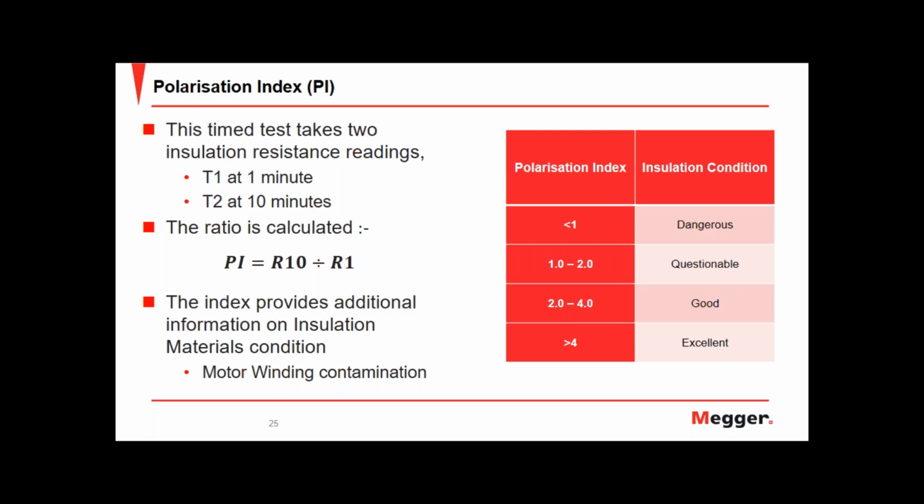So above 4, we regard this as an excellent polarization index. Below 1, it's dangerous and could fail at any moment.